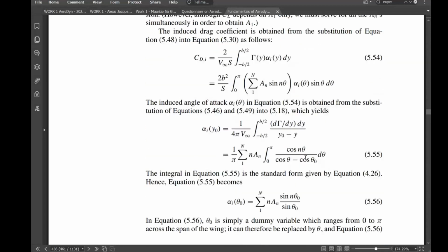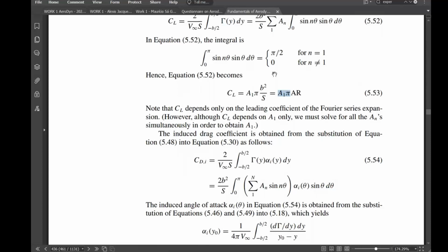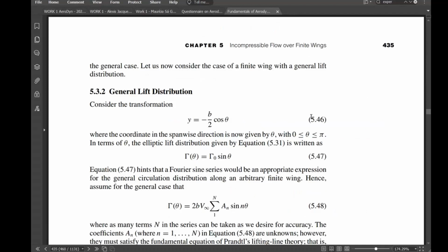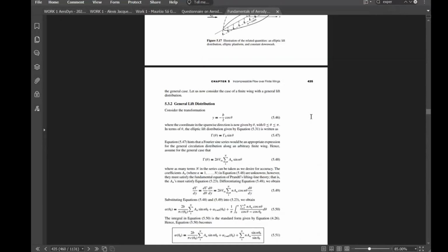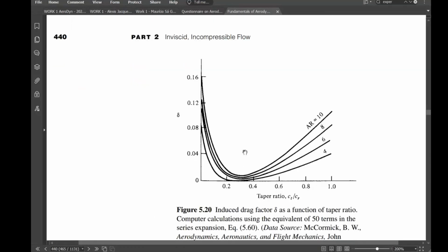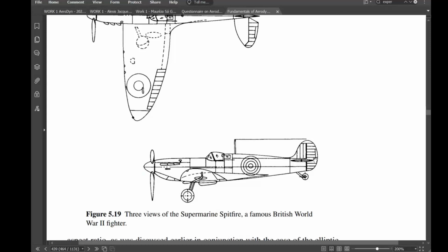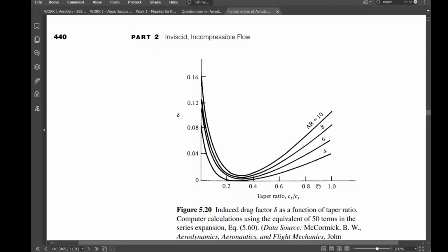See, so this is what theory says to us: the relation between lift coefficient and aspect ratio. It means that this theory can only be applied to a limited range of aspect ratios. Just a moment, somewhere here, very close, we have a plot that shows such limits. It was elaborated by Prandtl and team, and later improved. Such a formula can work efficiently for aspect ratios from, for example, minimum 4 to maximum 10. If you try to use it for an infinite wing or just an airfoil, it will not work perfectly.